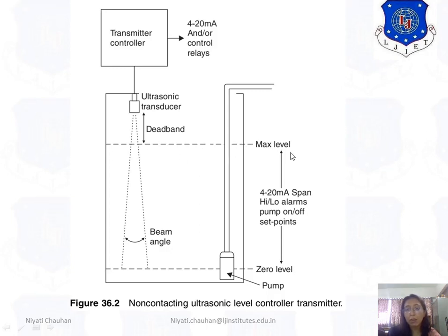This is the maximum level of water, this is the zero level of water, and this is the pump. Here are the 4 to 20 milliampere span, high and low alarms, and pump on-off set points.